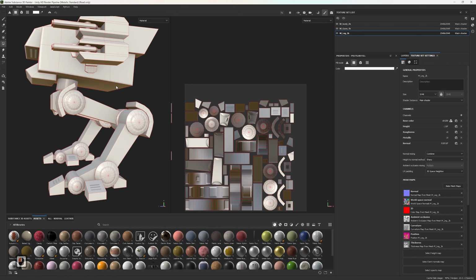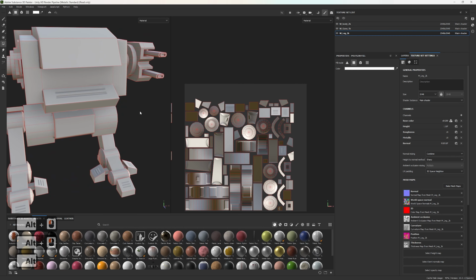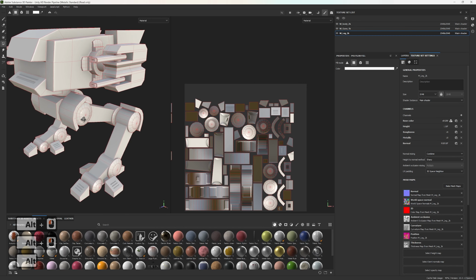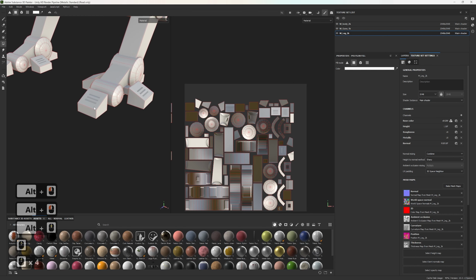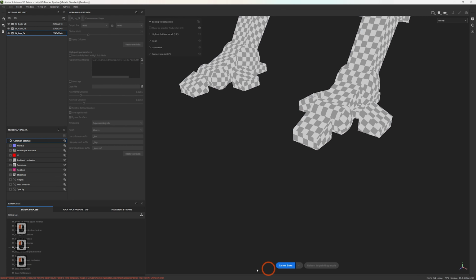Yeah, that's fine. I got an error because I was doing that, but that actually looks pretty good for a low bake. You also don't see weird shadows around the floating objects because of the ambient occlusion, since we turned it off. But I'm going to rebake at 4K and then the next time we come back we'll be texturing our model. So